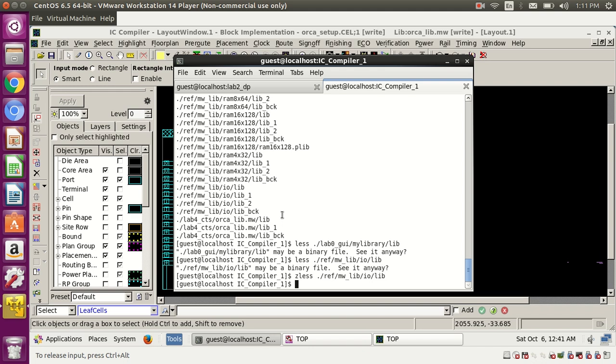If you know that, it is enough, because in future if someone asks whether there is any clock gating in your design, based on that you should say yes, this clock gating cell is there. That's it. Whether it is on by default or not, we need to maintain it. Clock gating will not be on by default, but normally you don't do it from scratch. In industry we don't load the netlist, load the DEF, load the SDCs, everything. One flow will be set, and from that flow all the inputs are obtained, like whether it is a clock gating design or not.